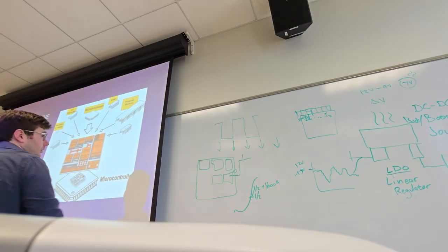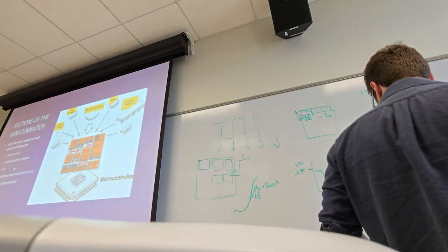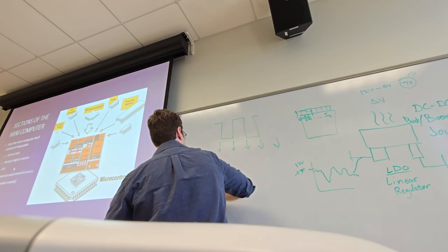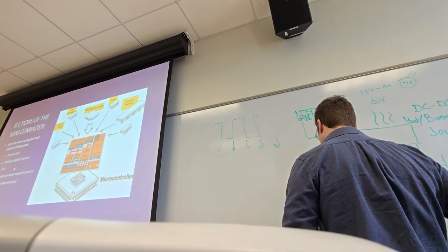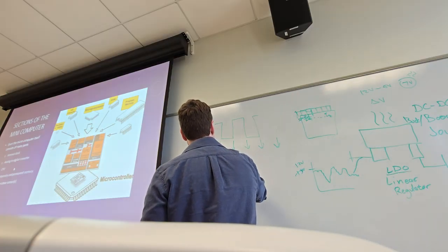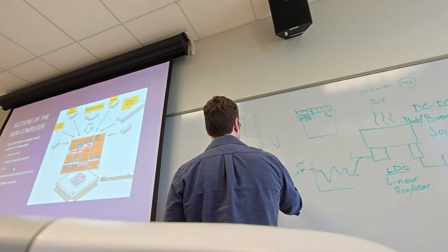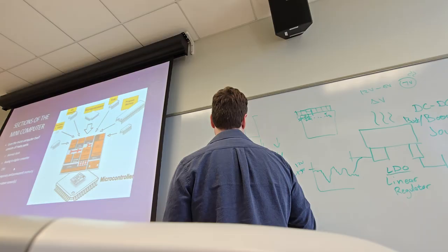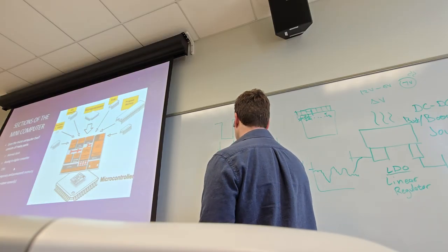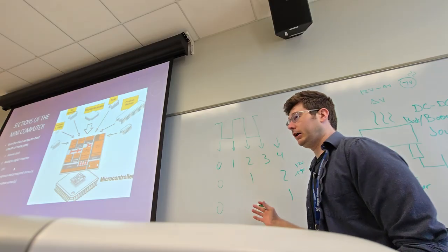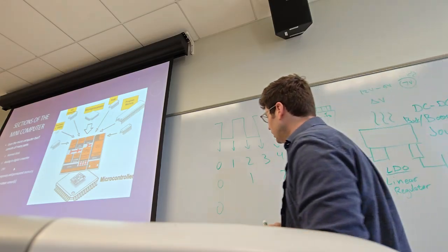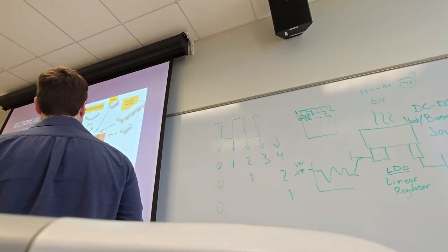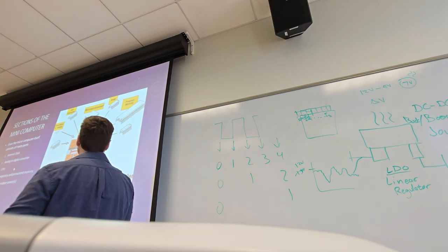Timers are actually things that cycle off of the original clock. So one timer, for example, will count the number of cycles and count up every time the square wave happens. Other timers will count every other square wave. Okay, there's different sets of timers and each of them does different things. They're great for generating clocks. PWM, servo timers, all that stuff is generated with these timers.